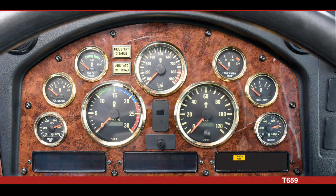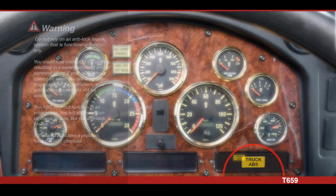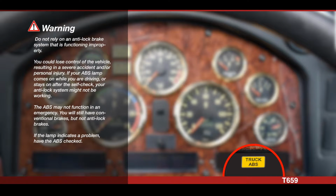Truck ABS. This lights when the ignition is on and stays on for a short time. If this light is on at any time during vehicle operation, it signals a fault in the anti-lock brake system. The ABS may not function in an emergency. You will still have conventional brakes, but not anti-lock brakes. If the lamp indicates a problem, have the ABS checked.